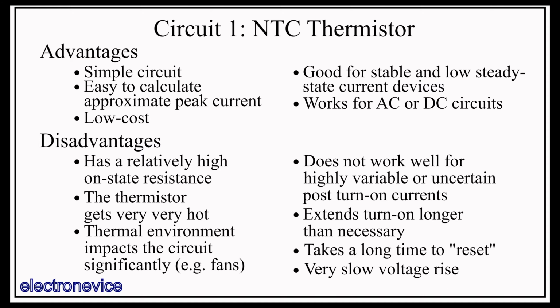We'll return to this point later, I'm just foreshadowing right now. There's a significant time delay between the turn-off and the point at which the circuit is reset and ready to accept another turn-on transient. If you turn off the system, then turn it back on only a few seconds later, it will draw a significantly higher inrush current since the thermistor hasn't cooled down yet.